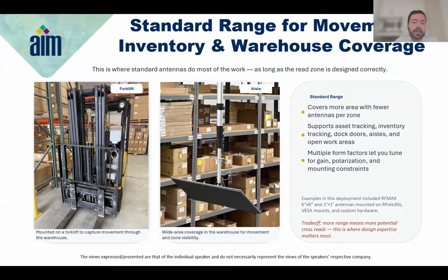Metal is one of them that can bounce or block the signal, liquids, sometimes carbon fiber. So again, you really do need an expert because there's so many standard range antennas in the market. It's critical that we choose the right one, whether that's range, gain, deciding if we need circular polarized versus linear. Again, we have that experience, that expertise to help guide you in the right direction as to what we think is the best option and then test in your environment.